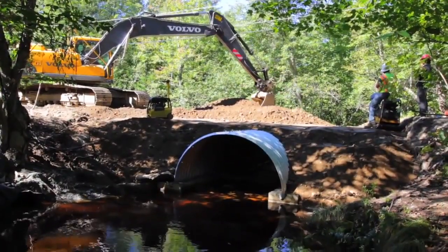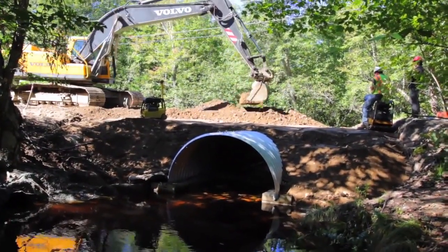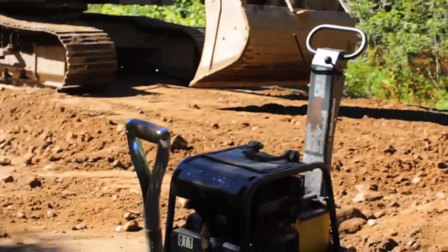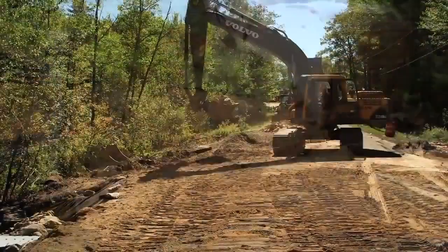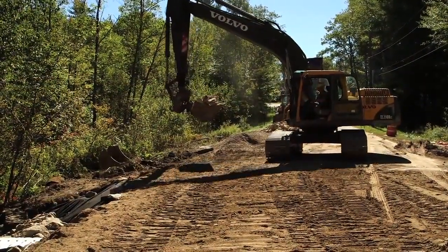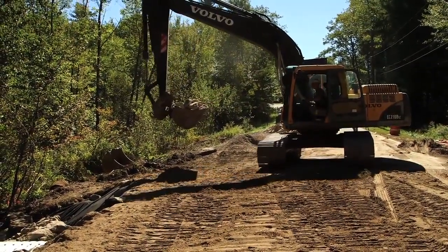Even though the road fill beyond the culvert envelope backfill is typically not mechanically hand compacted, it still should be placed in lifts no greater than 12 inches with adequate compaction between lift placements. This will help to minimize settling in the road surface, especially closer to the culvert.